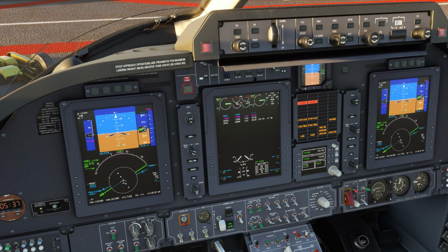7126. Rescuer 112 cleared to Oxy Airport as filed. Takeoff runway 08, climb and maintain 10,000 feet. Departure on 135.45, squawk 7126. Rescuer 112, read that correct. Contact ground on 119.0. Good day. Right. So transponder is set.